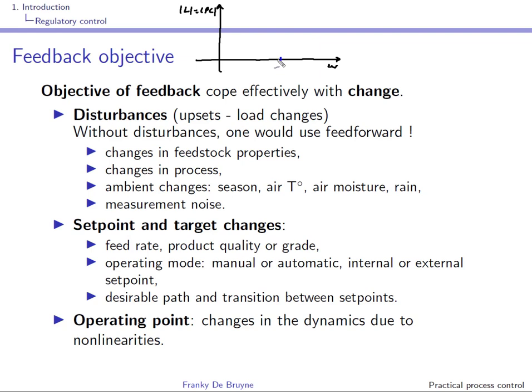So you have here the crossover frequency, you have a zone where the slope is around minus 20 dB per decade. Then in the low frequencies you have a high loop gain, probably because you have put an integrator in the controller, and then you have a high roll-off. So this is here the crossover frequency, right?